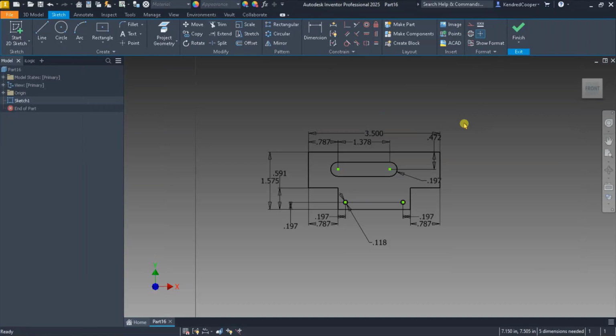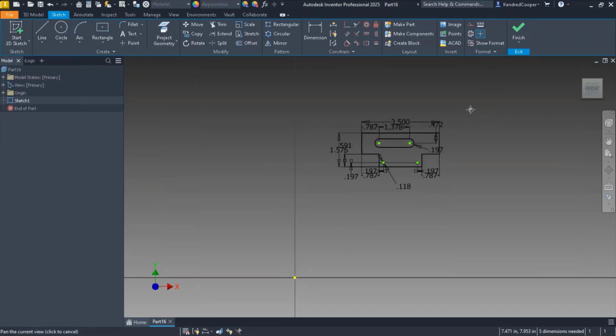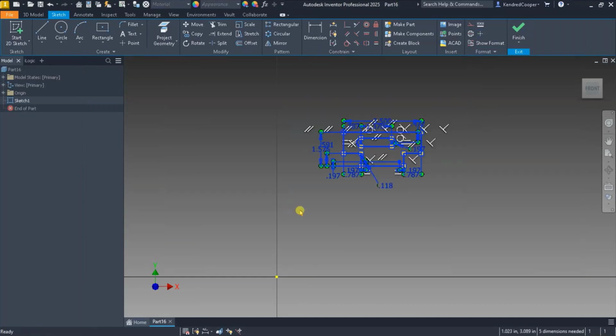If your AutoCAD drawing has multiple or all of the dimensions exploded, then you're probably going to be better off time-wise recreating it from scratch in Inventor, because there's going to be a lot of cleanup to come through here and get rid of those exploded dimensions. So you can use that utility to bring in your AutoCAD stuff. But again, I don't use that utility simply because I don't like waiting on it to fire up. Now, the first time it fires up, it's slow, but gets faster every time after until you shut down Inventor.